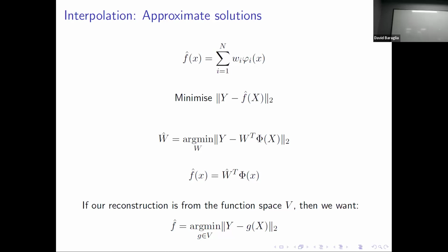So you can do this using sinc interpolation, so Shannon interpolation. You no longer use Shannon's interpolation formula, but instead you can solve it this way. But what's more common in practice is passing a signal through an anti-aliasing filter, which is ideally an ideal low-pass filter, and then applying the Shannon interpolation formula after that.